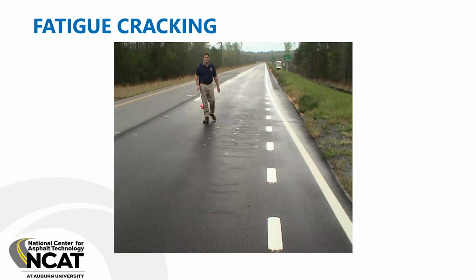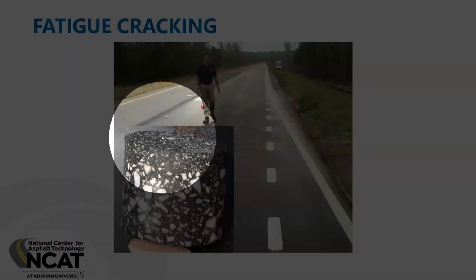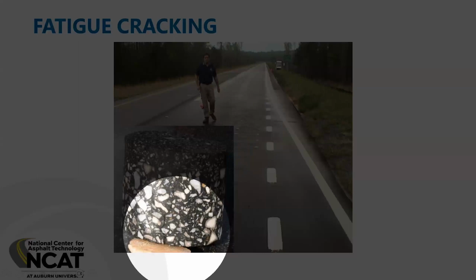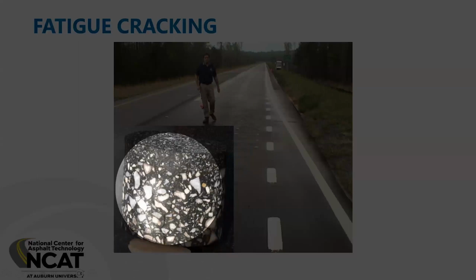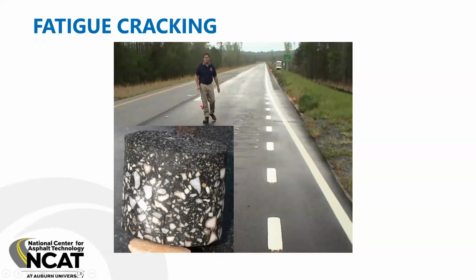And that's virtually a universal truth when you have classic bottom up fatigue cracking. In the case of this experiment, we cut cores. If you look real close to verify this, you can see an arrow in the direction of traffic in the wheel path. And as I said, this is a bottom up fatigue crack, and is working its way up to the surface of that pavement.